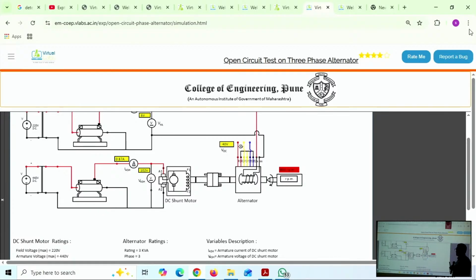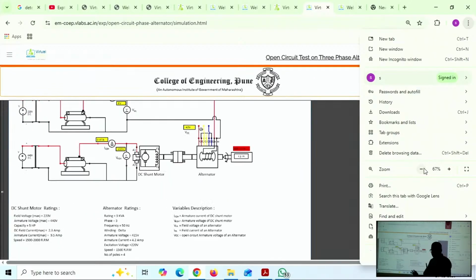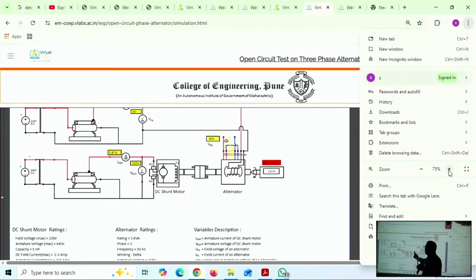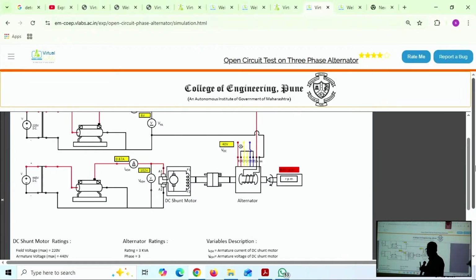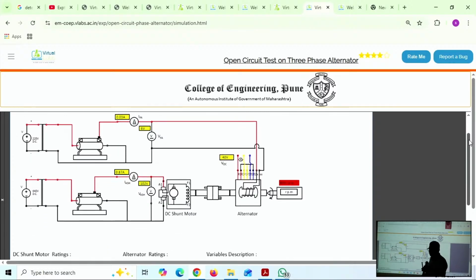Open circuit test. Okay, now short circuit test. Just after knowing this, the short circuit test should be taken with even more care. What common mistake will students make? Here you took it up to 400 volts open circuit. After that, what do students think? Make it up to 400 volts, then short the armature terminals. I used to show them practically: we increase now to 415, short circuit, let us close, and they will say close.